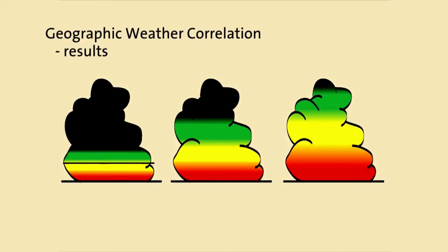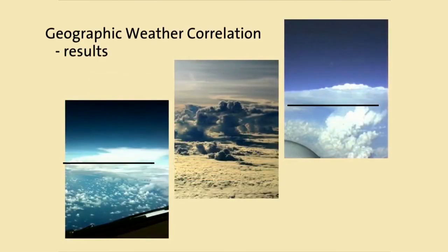In regions where thunderstorms display strong reflectivity characteristics, thresholds are set higher to prevent the radar from overwarning and causing unnecessary deviations. Thus, thresholds are matched to weather characteristics in a particular geographic region to determine the actual cell height and to best display the actual thunderstorm threat.